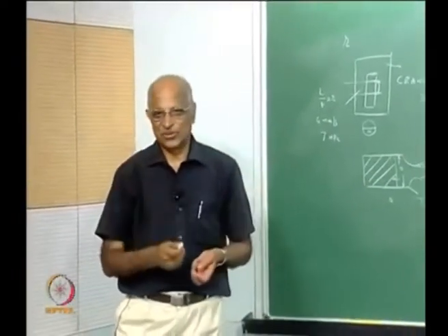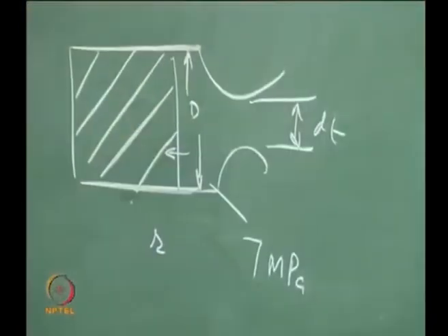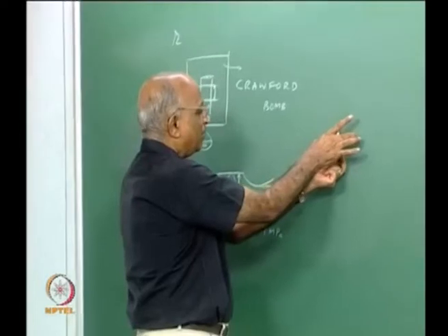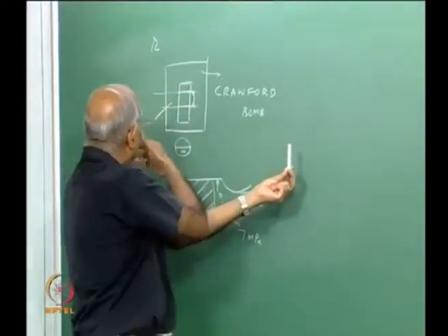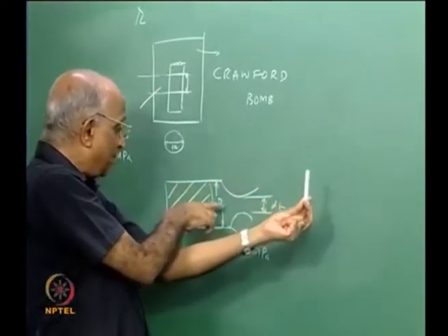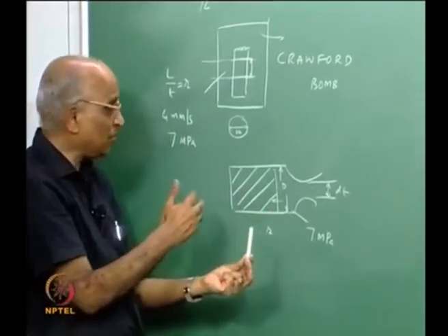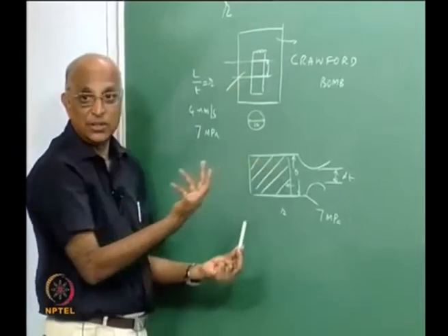What is your take on this? How would you feel? Should it be the same? I measure in a strand, I put it at the same ambient pressure, and I measure a burn rate of 4 millimeters per second at the same pressure as over here, and I want to measure the burn rate in the motor, because I use this to be able to design it.